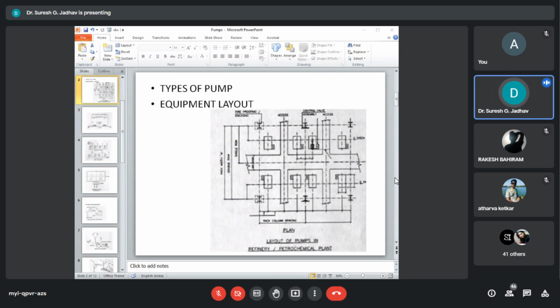The extent and frequency of pulsations depend upon the number of cylinders in parallel and whether they are single or double acting. Due to pulsing operation, these pumps are bulky but are considered for very low flow applications. The pumps could be single acting with a single piston plunger with very high pulsing flow. The variation in cylinder arrangement gives single, duplex, triplex, and quadruplex pumps.